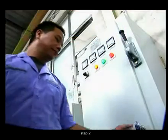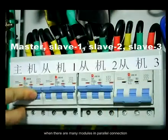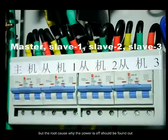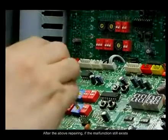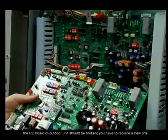Step 2. Check if some outdoor units are instantaneously powered off when there are many modules in parallel connection. In this case, the malfunction can be solved as long as the power supply resumes, but the root cause why the power is off should be found out. After the above repairing, if the malfunction still exists, the PC board of the outdoor unit should be broken. You have to replace it with a new one.